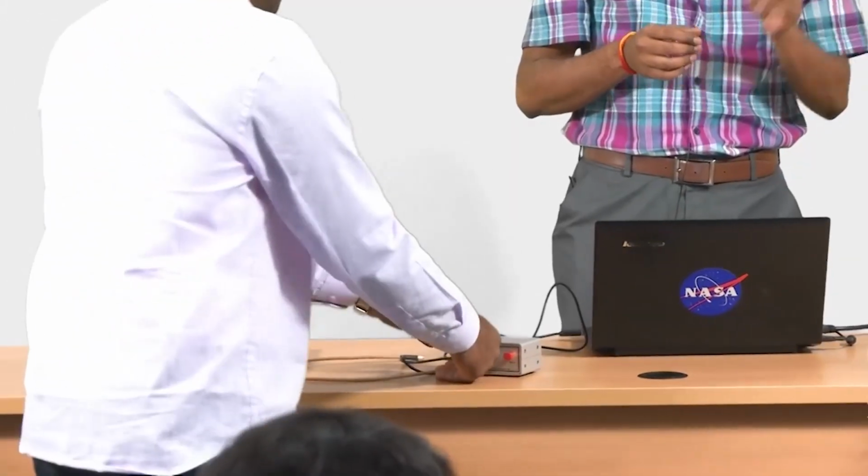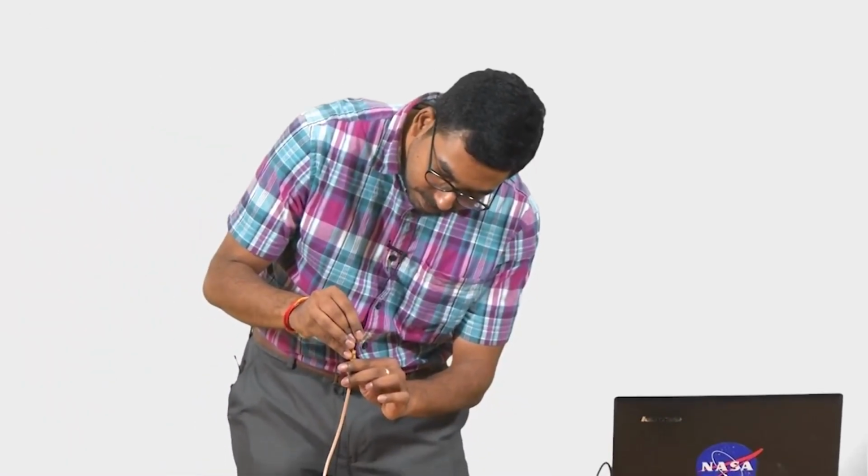I have a couple of resistors that I have braided together. These are 200 ohm resistors, I think. So in parallel I have connected them, so they should be 50 ohms. But 50 ohms at what frequency? Usually when you buy 50 ohm resistors, that is for very low frequencies or DC. So now we are connecting this at 100 megahertz.